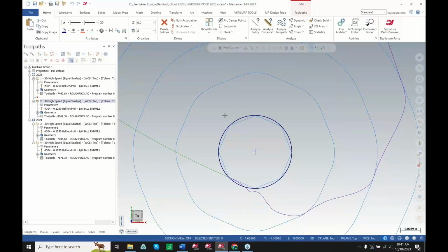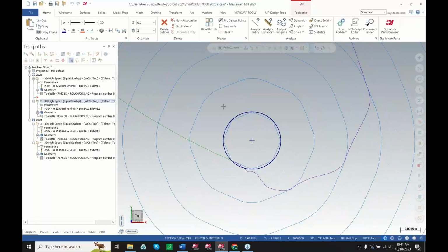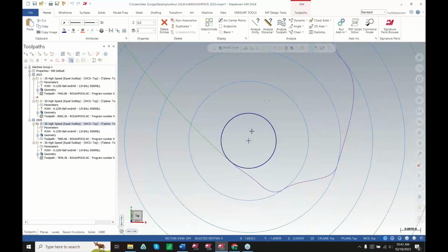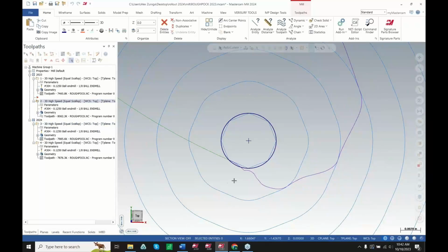The only way that we could have potentially made this better is to go into our configuration and raise the tolerances and the main system tolerance. That is now no longer needed in 2024, where we are able to just regenerate the toolpath. We have ourselves a nice smooth looking toolpath here. You can see it's not comparable to the original here.